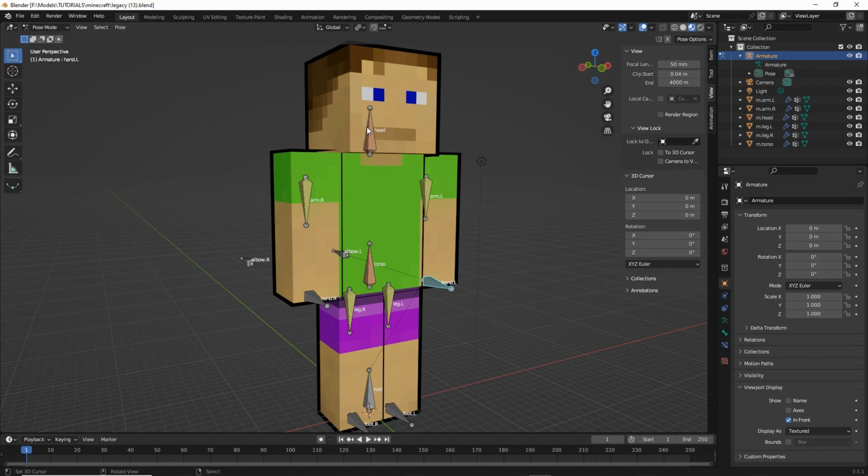So what we might want to do first is create a pose rather than necessarily a complicated animation, so that we can test the rig and the constraints, make sure that they are working the way that we expect them to. To make the process easier, what we want to do first is enable and edit the auto insert feature. So we want to enable auto insert in the timeline header. That's step one. Then in keying, we need to set the active keying set.